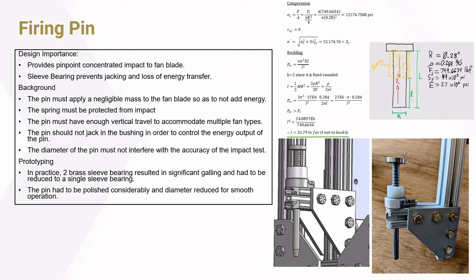The design includes a compression spring that acts as a reset and allows the firing pin to automatically start at a higher point and return to that point after impact, which is nestled between the head of the pin and the plastic spacer to prevent overcompression.